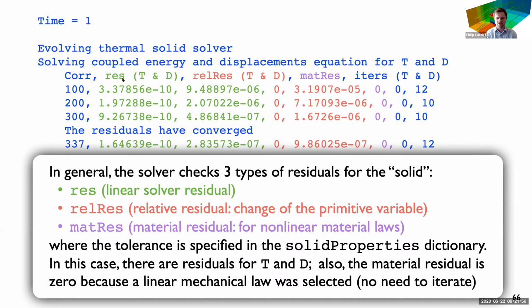For example, if you're solving for temperature and temperature is just 0 everywhere and all the boundary conditions are 0, then it's hard to calculate a normalization factor because it will be 0. So you might get a residual that's large and not changing, even though the case is converged. So just having 2 of them makes it a little bit more robust. At the end, it's just printing out the number of inner iterations required at each stage.